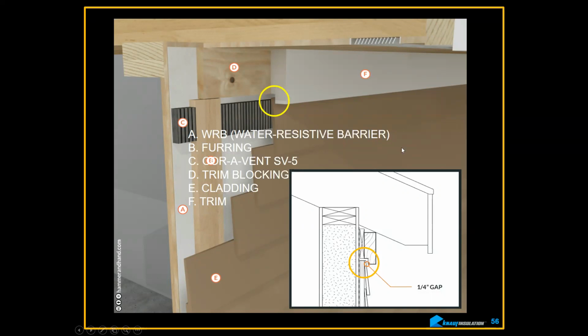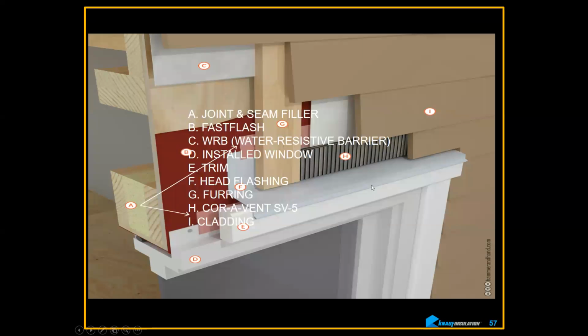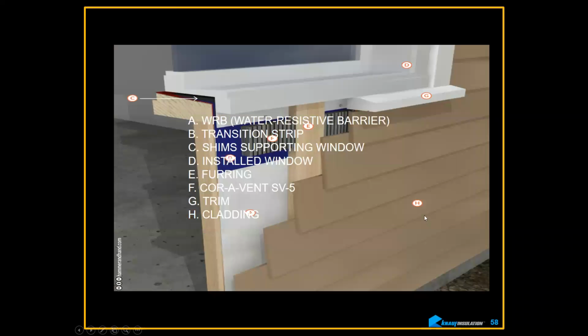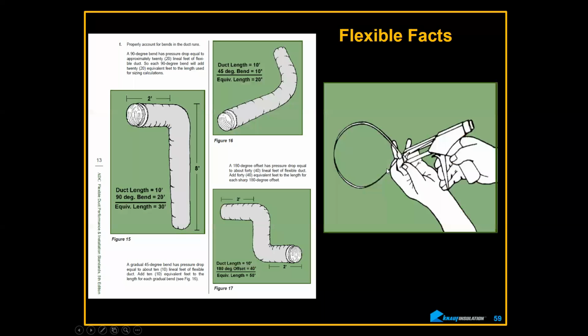This is again over the top of the window. Same thing on the bottom of the window. It's disconnected from below. So you have to make sure that any moisture that gets in here goes up. This is how you deal with it on the bottom of the window. Same thing. Slopes and weather-resistant barriers, tapes, sealants. Again, everything is shingled over the next layer. Just to show you that this should be sloped in here. All those leak, every single one. Brand new, brand old, doesn't matter. They all leak. Otherwise, they wouldn't have weep holes in them.